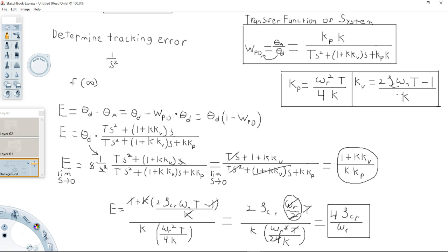But how you would solve the tracking error, or if tracking error does exist, in this particular case, you can add an I controller, and that would effectively bring the tracking error down to 0. In all cases, you want the error as time reaches infinity to be 0. You never want it to be some remaining value like it is right now. So again, to reiterate, how you would solve this error would be to add an I controller.